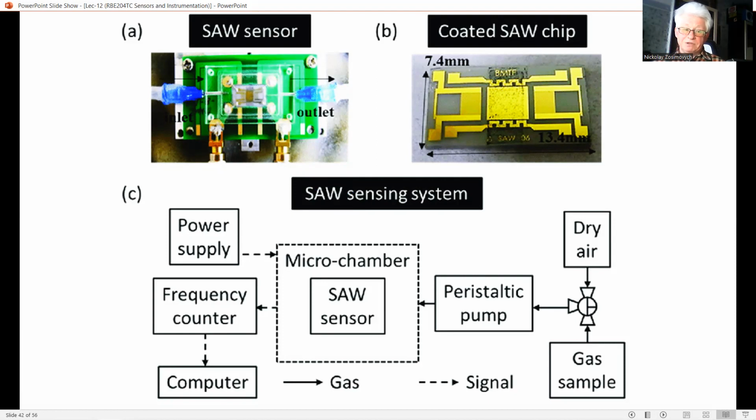The SAW's velocity, or surface acoustic waves, is influenced by the concentration of the absorbed matter, and such SAW devices are suitable for the chemical sense. The selectivity is greatly determined by the chemical interface. And in this lecture, we only discuss acoustic sensors for the measurement of mechanical quantities in mechatronics, where the propagation medium is generally, as you remember from the first part of our lecture, air.